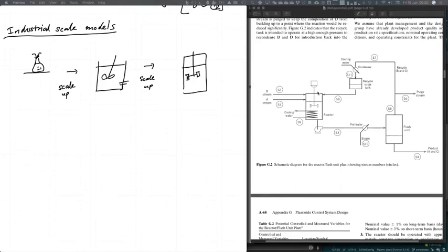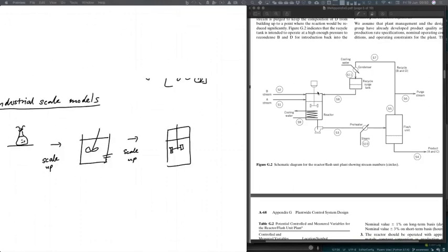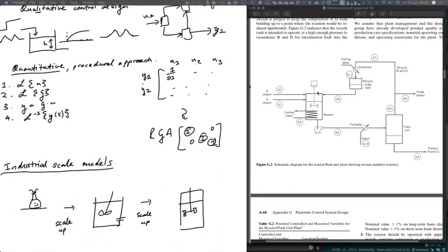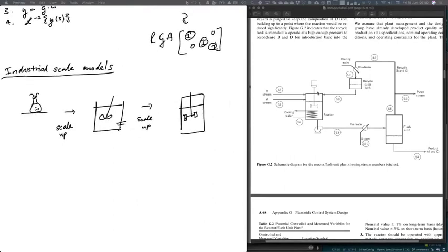So how do we do control design when we don't have models, right? If we don't have these beautiful techniques that we've discussed over here, where we can do quantitative results and do Laplace transforms and RGAs and the like, what do we do instead? Well, it depends on what part of the design process we are in. If we are in the design phase, in other words, if this process has not yet been built, the best we can do is to reason through the connectivity of the physical diagram.